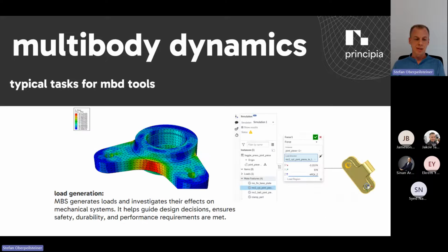And last but not least, load generation. This was or is the main task of MBD, namely to generate realistic forces, inputs, so interface forces, in order to investigate the structural deformations and stresses with finite element analysis. So usually this is a two-step approach.